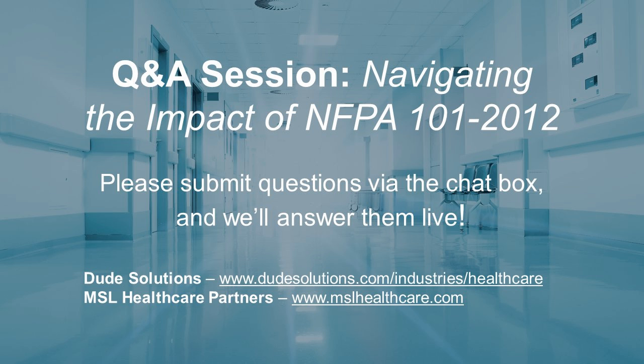I know you mentioned earlier that Life Safety Code Chapter 43 allows us to convert a patient room into a storage room by adding just a door closer. Does this require a 45-minute rated door? I know this might go a little bit along with the last question, but does it require a 45-minute rated door and 1-hour rated walls from deck to deck?